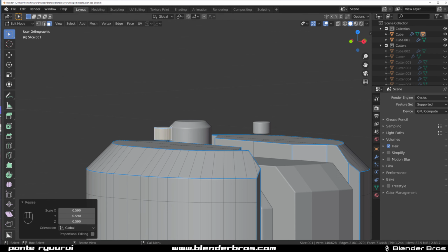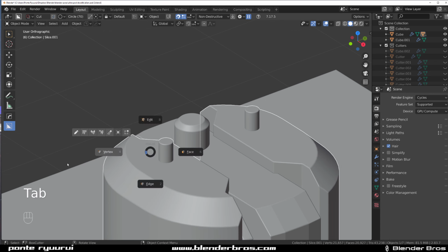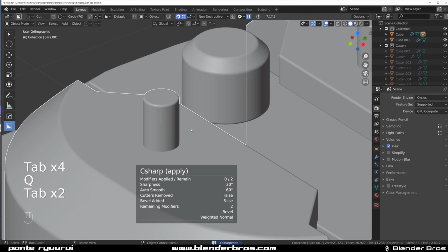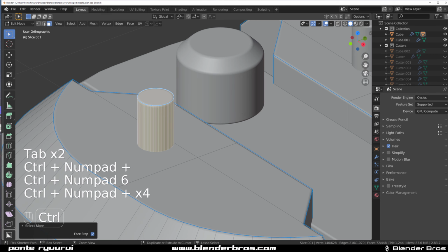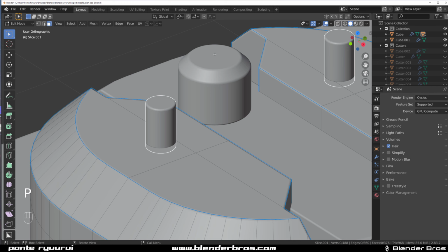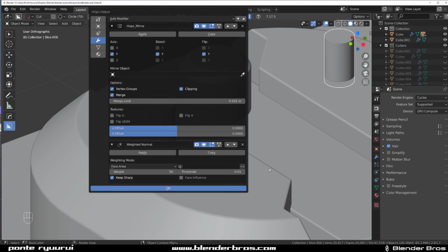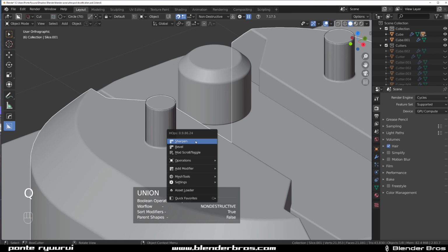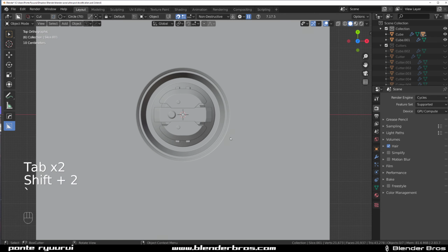And they're not connected, are they? So let's make them bigger. And now they should be linked or not. Let's just sharpen this and this one as well. This mesh is not joined, is it? Nope. Okay, so press P, select to its own selection, select this one and then remove the bevel and remove the weighted normals, and we can actually keep the mirror, so union, and then sharpen this one and we're done. So that will do. Shift 2 to remove them and we're good.